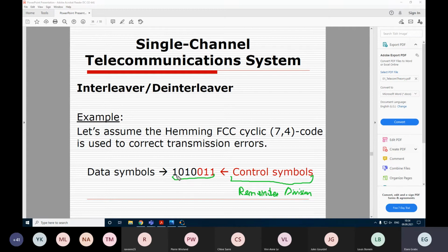Then at the receiver side, we again separate these data, again calculate division, again find remainder, and compare this new remainder, which we calculated, with this reference remainder, which has been sent alongside with our message. And this way we find where the error has happened. So this is the brief idea.